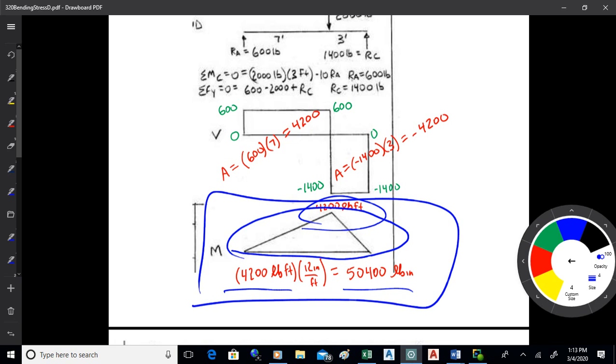And a good example of that would be those truck trailers, those flatbed trailers I was showing you a couple days ago. It's worth it to build them that way, because you build so many, and you'll get cost return on that for putting those wheel wells in there and carving the beam out near the wheel well, because you don't really need that structure there. Okay, so just something to be aware of. But in the civil world, you just don't do that as much.